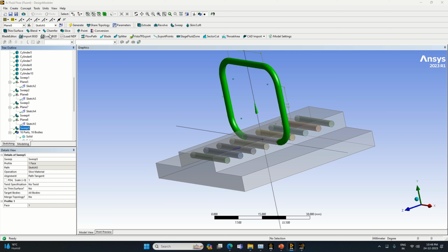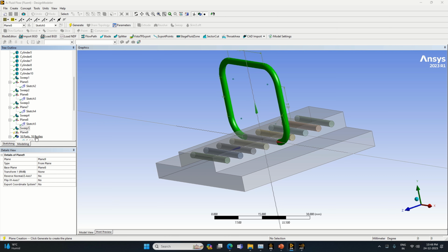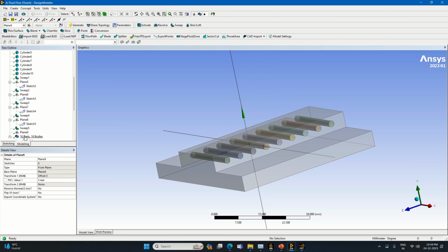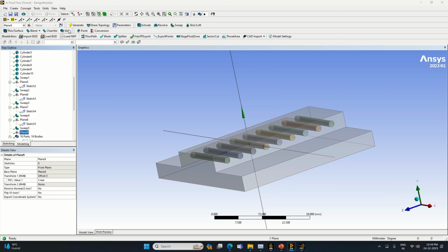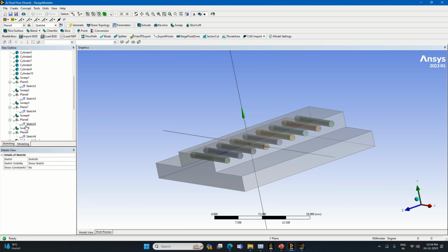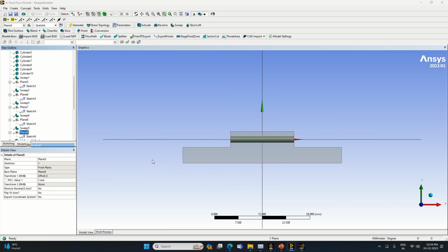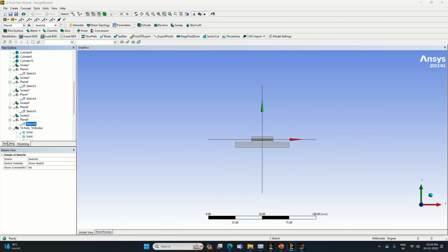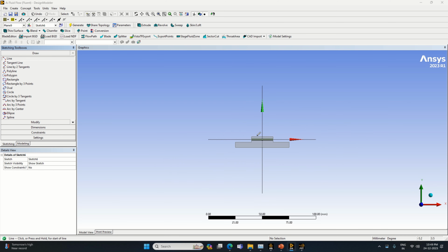So now one more time create one more plane. From plane 8, let's take offset z, that is equal to 5. So you will see, you will reach the next location and make it generate. So for this plane again we need to prepare the sketch. So let's look at the plane. So for the sketch again follow the same thing which we did earlier.